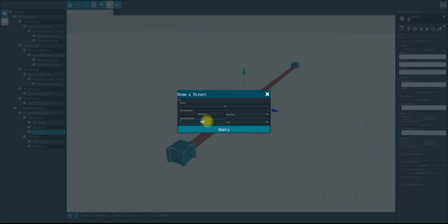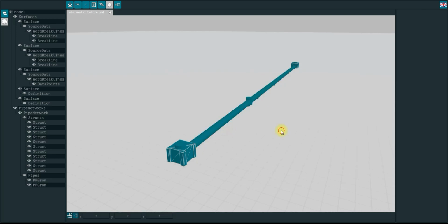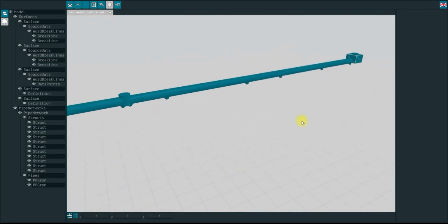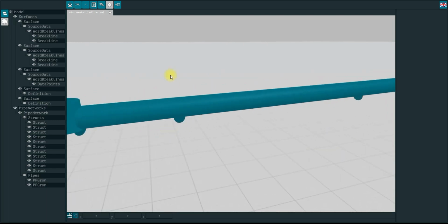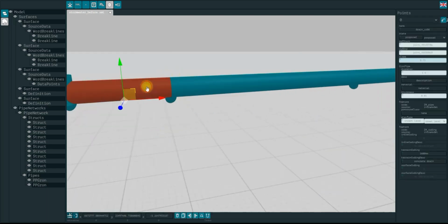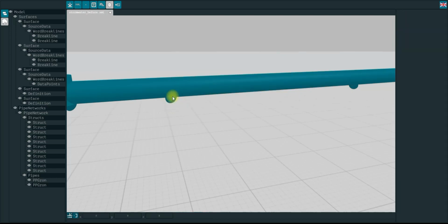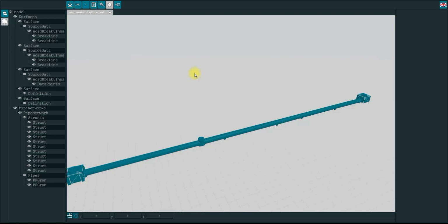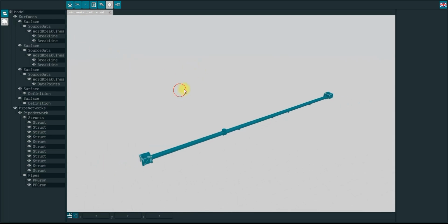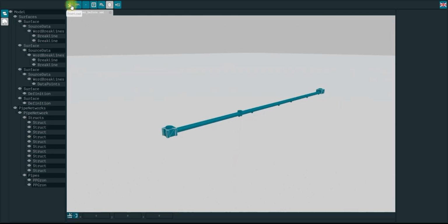And then there's down here, there's a field called connection. You want to choose yes instead of not, and then you press apply. And then you see in each of the connection where 2 pipes connect, it added those small symbols there. It means those pipes are connected. So then you might want to press Ctrl S one more time, and then your 3D model is good to go. You just download it.